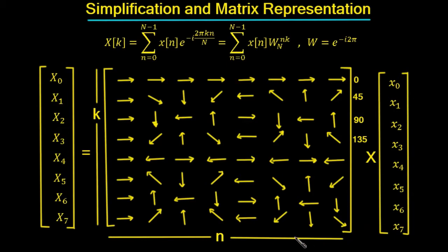So in the discrete Fourier transform, our function x of n modulates these at values here, and then we sum up the values with respect to k, so we sum them up in this direction. So this part of the matrix here is our w of nk sub n, and you can see here that we're going to start up in this corner here, so n and k are both 0, and then as we move along here the k remains 0 but the n increases.